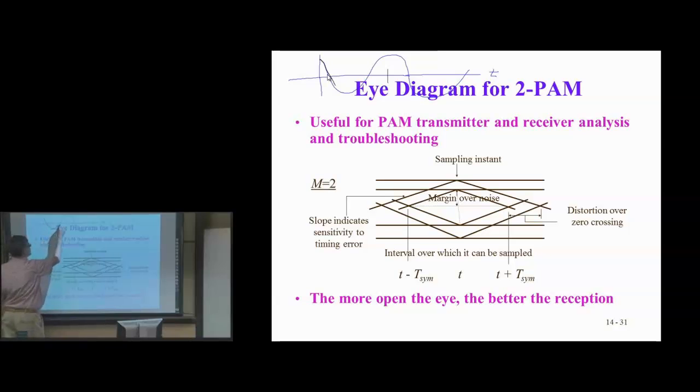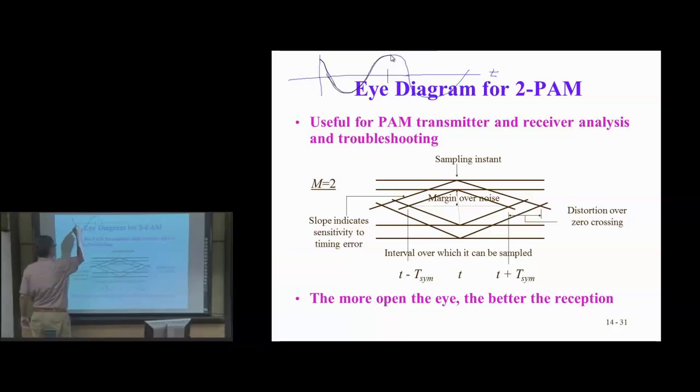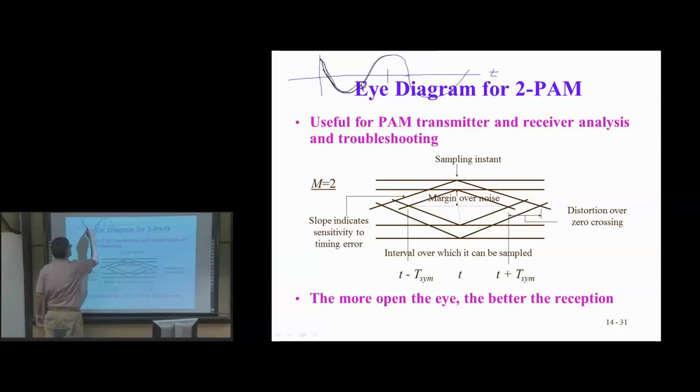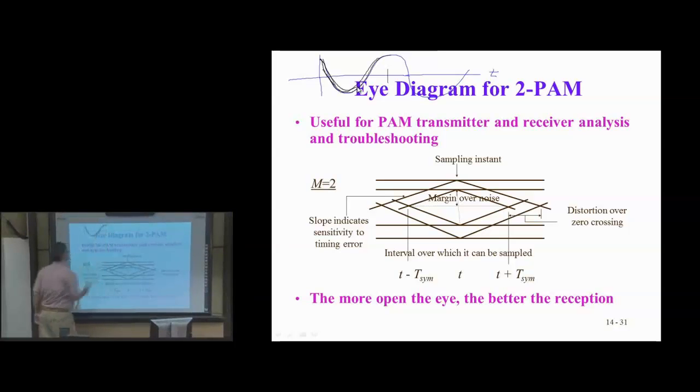If you do this over time, you'll start seeing any jitter in the phase. If there's any distortion in the waveform, maybe noise being added, then over enough time you'll see all the distortion over that period of time. It's hard to visualize if you just plot it as a trace. But if you superimpose and trace over every period, so you go here, and then the next period gets traced over the first one and so forth, you'll see the distortion.